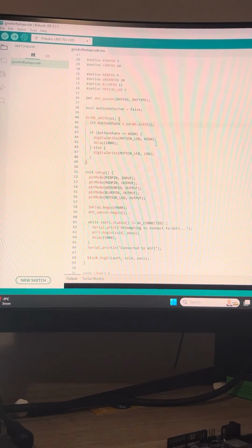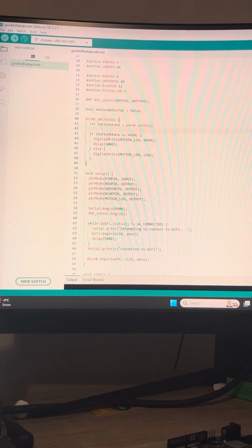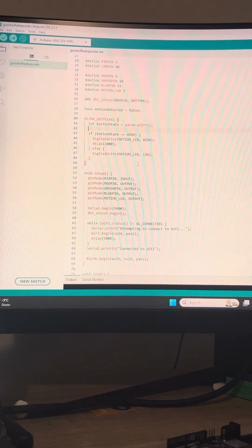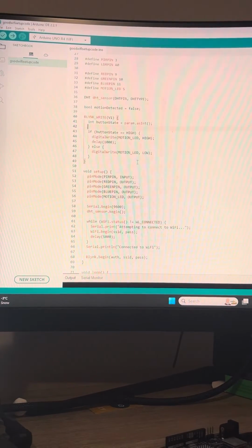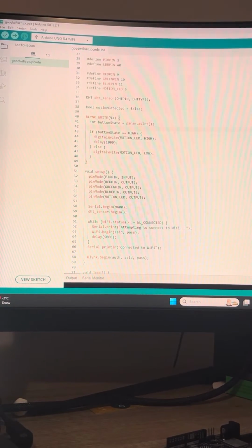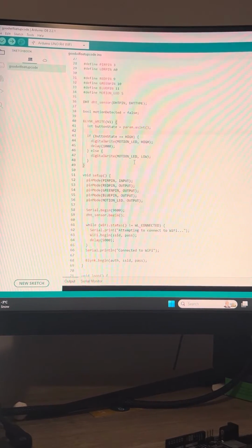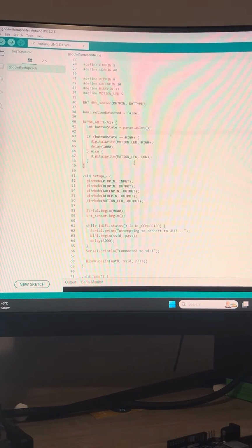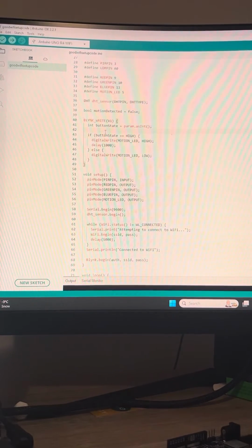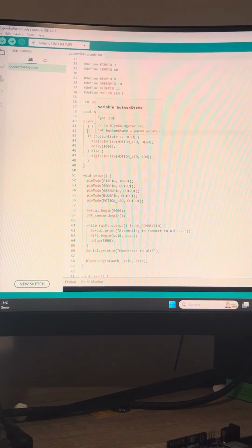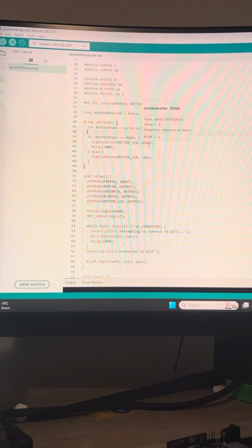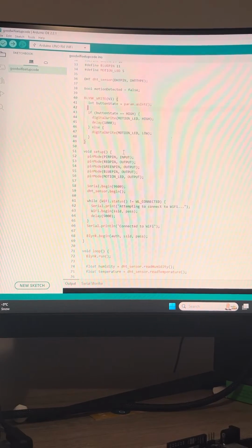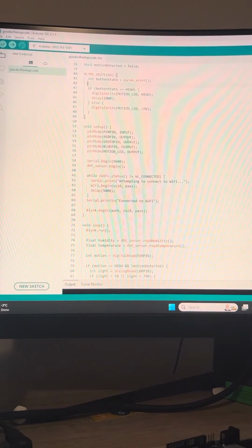So V1 is a digital pin used for the Blinks app to allow communication from your device to the circuit itself. So the only digital pin that I have is the button on the app that you could see in the previous video that turns on the LED as a test. So it checks here if button state equals high, LED is high, and it turns on the motion LED, our large 12-volt LED, in other words.